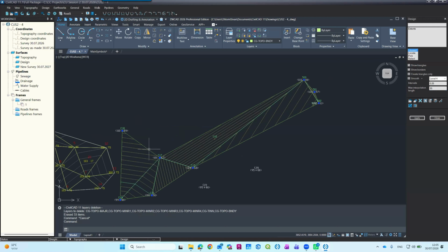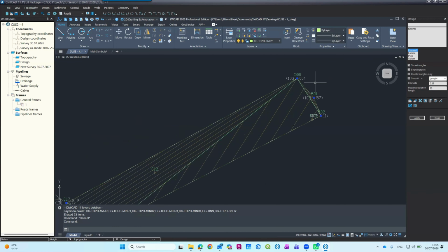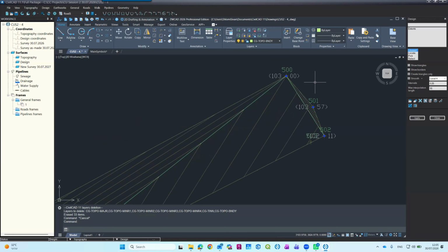So, okay, I have this boundary. I can take it, again, do p-edit and remove additional. For example, here, I don't want this one. Okay, so I'll do the same thing. P-edit, edit vertex. So insert. And this is the new boundary. I'm selecting it. Not this one.